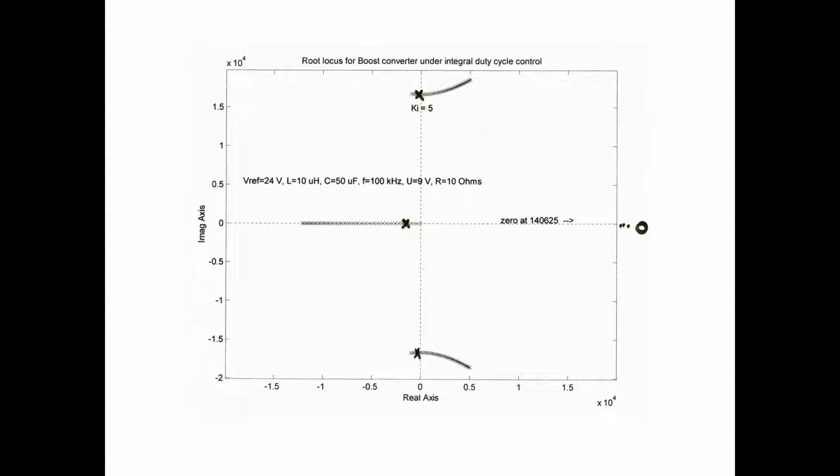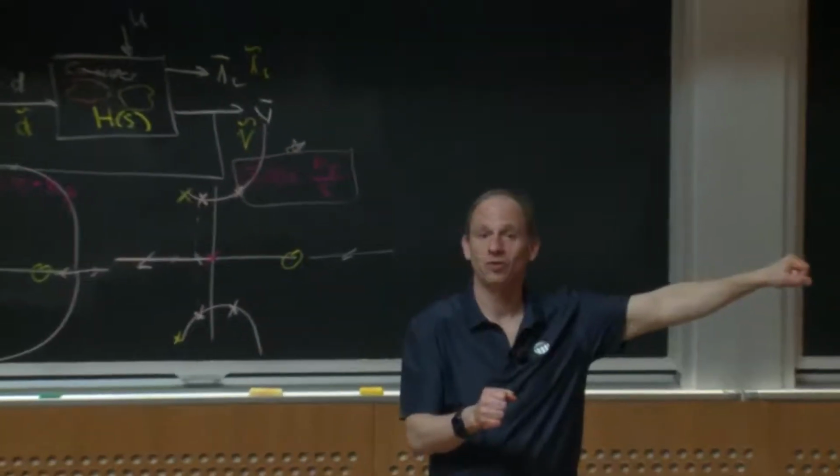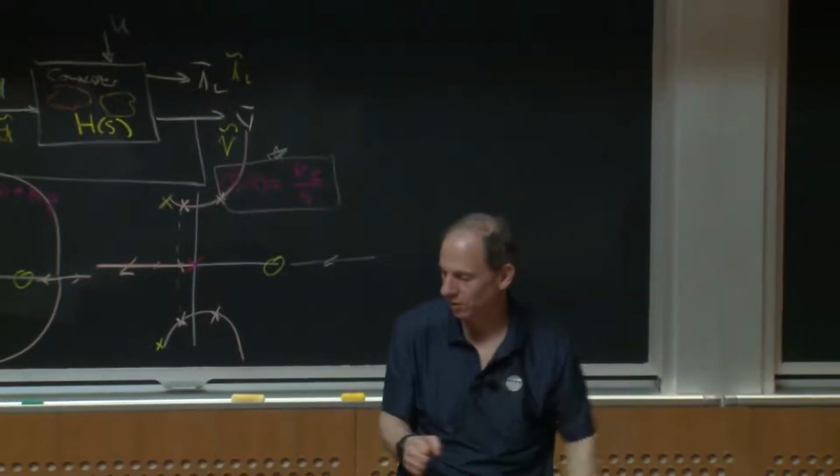And I have a pair of super lightly damped poles here, okay? I could then say, all right, let me calculate the closed loop pole locations. That's how, once I have the feedback loop, if I kick the output, that's how it'll oscillate once it went with my control system in place, okay?